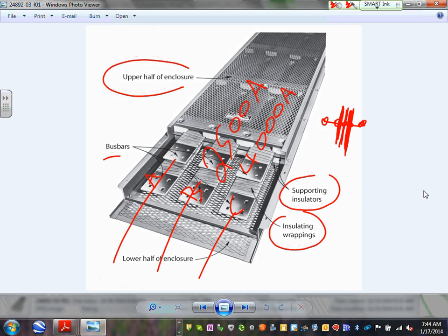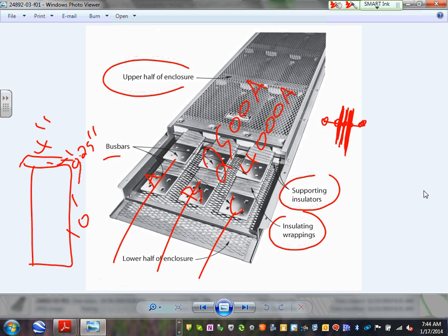But the most important thing is that you can see here's the bus bar that I carry, exactly like in a panel gear. Say this is 4 inches, and let's just say a depth of 0.25 of an inch, and the length is typically 10-foot sections. That's what you're looking at. You're looking at a 10-foot section for this bus bar.